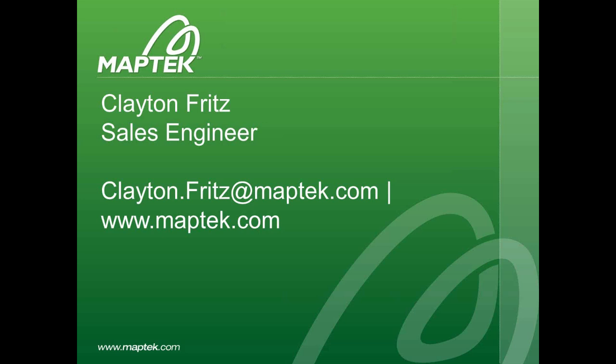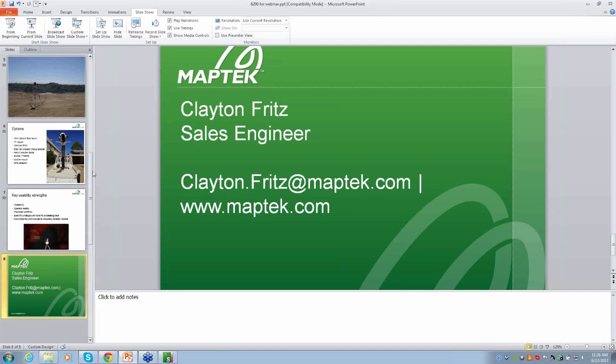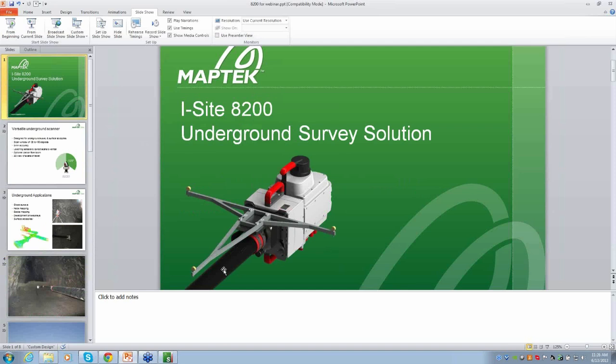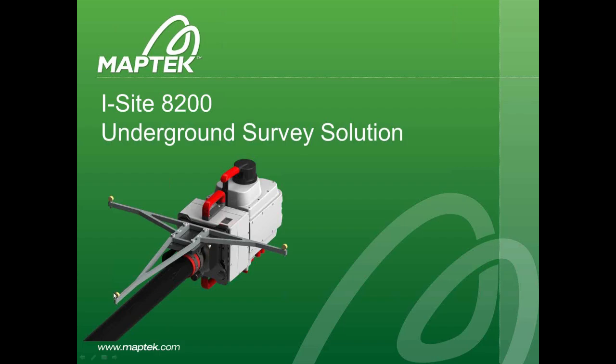Okay. How do you locate or survey in the scanner position, especially when it's out on a stope? That's a great question. I'm going to bring up a different picture here that shows how we do that with one of our options. You have several options. One is this T-bar, which is one of the options that comes with the scanner. There are these 3 brass reflector points, and you shoot those in with the total station. It's specifically designed to automatically register. There is a T-bar registration algorithm within the software.